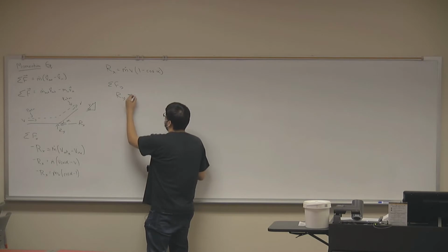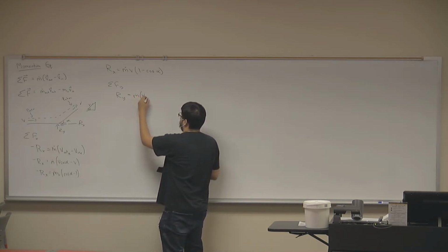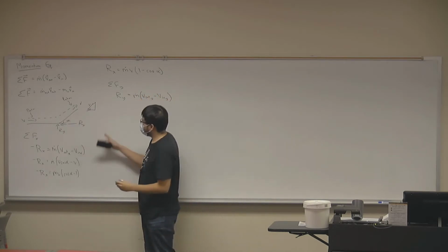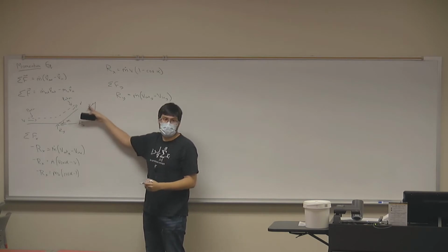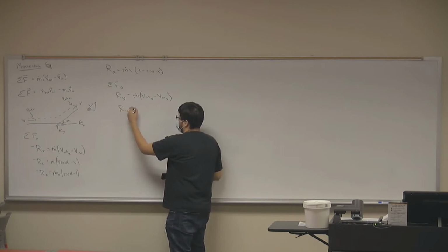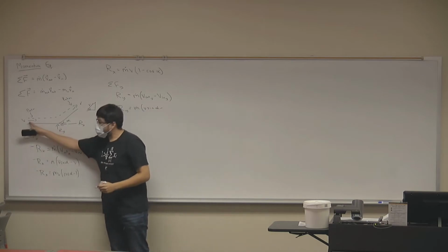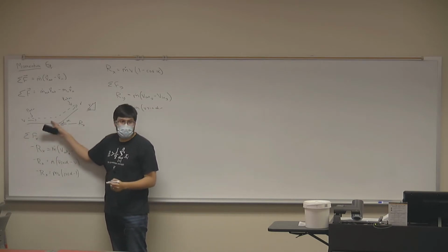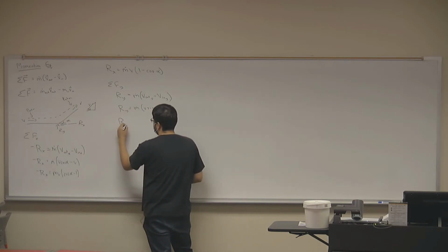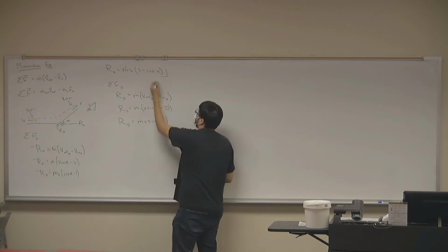And that was equal to mass flux times velocity out in the y direction minus velocity in the y direction. And here we see that the y component of this velocity is just velocity times sine of alpha. Is that correct? So we get that Ry is equal to mass flux times velocity sine of alpha. And then we get that the y component of the velocity entering my deflector is what? 0, right? So I get an equation of Ry equals mass flux times velocity times sine of alpha. So these were my two deflector equations.